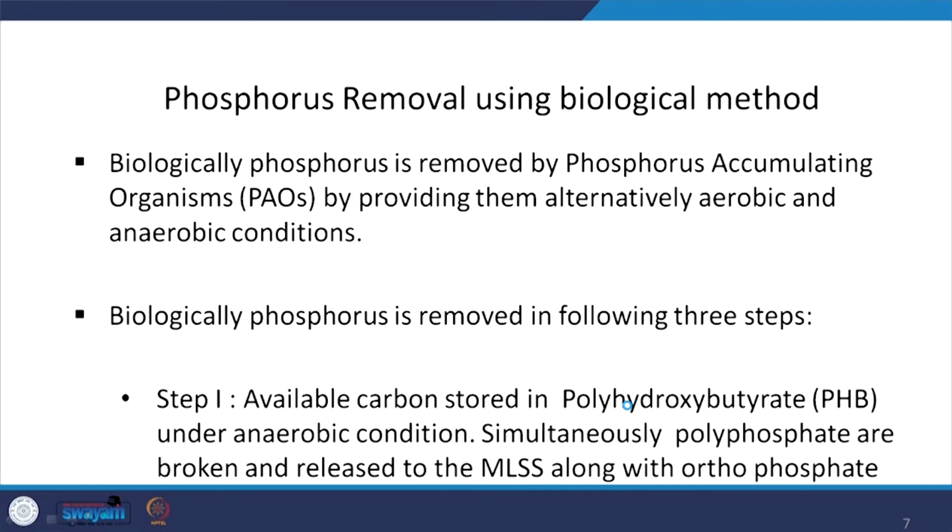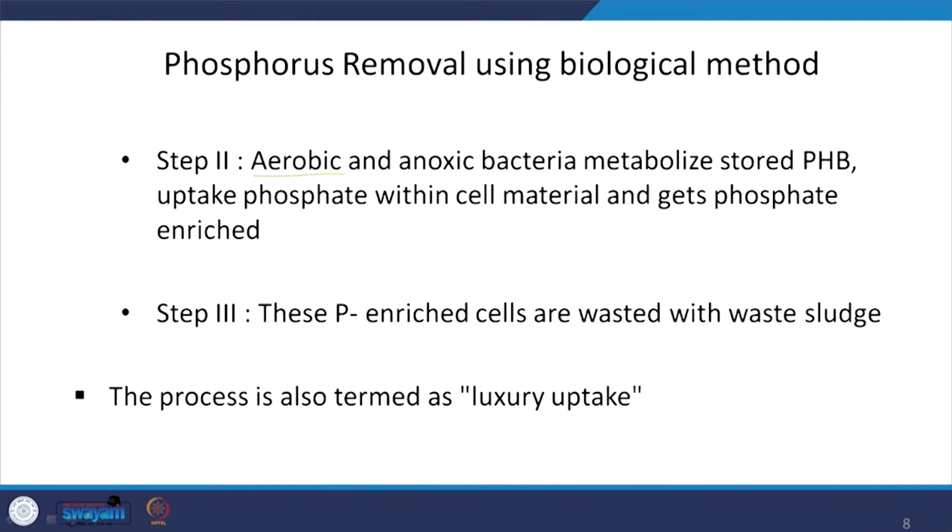So, phosphorus removal, as we mentioned, I guess I can skip this aspect. Let me see if I talked about the fermentation byproducts. Okay, in anaerobic conditions, let me just highlight this. Under anaerobic conditions, phosphorus or orthophosphates will be released. Under the aerobic conditions, we will have phosphorus being taken up, uptake. We can also look at the details.